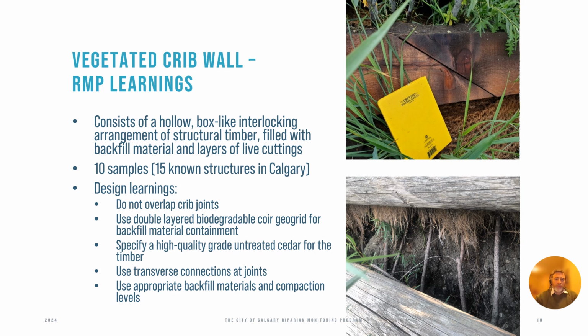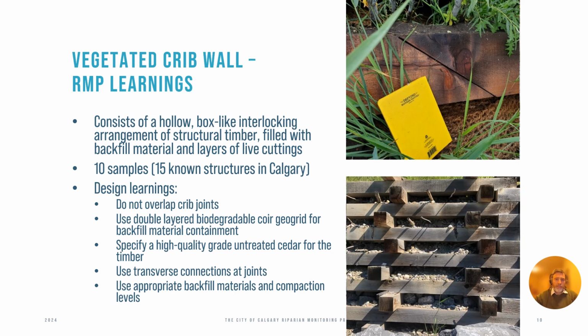Specify high-quality untreated cedar for timber to ensure long-term durability. Use transverse connections at joints to shed water rather than notches that trap water and degrade timber. Choose erosion-resistant backfill materials that support vegetation growth and ensure proper compaction to avoid limiting plant establishment.